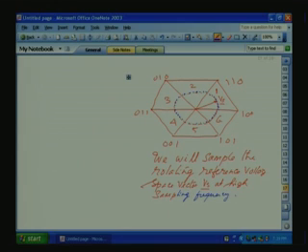That means instead of continuously tracing, Vs is making small jumps as shown by the dots here. That jump depends on our sampling period. During a sampling period, once it is sampled, till the next sample, we assume the Vs amplitude and angle are stationary.